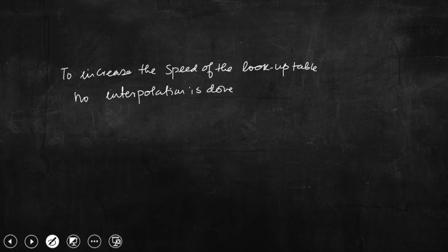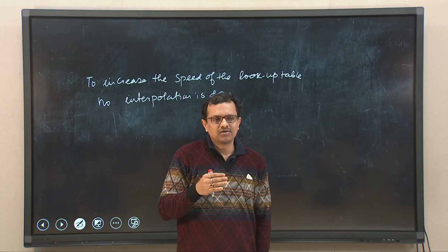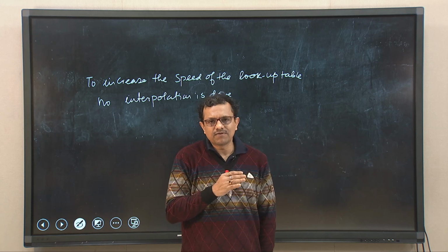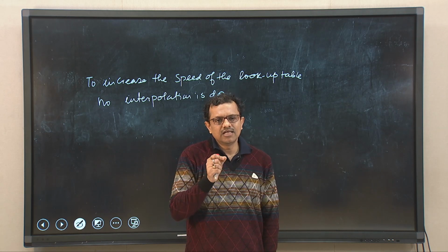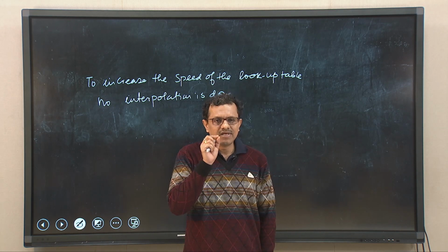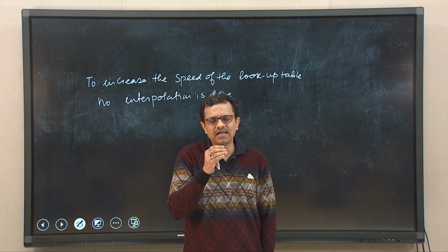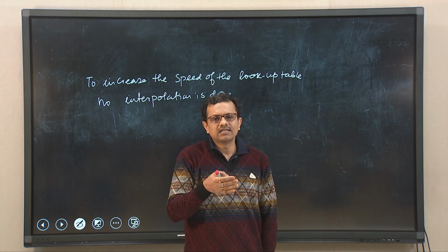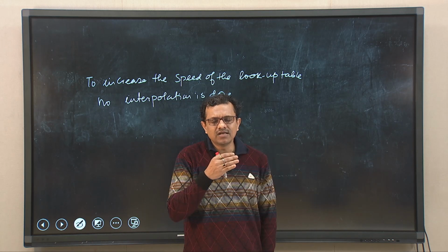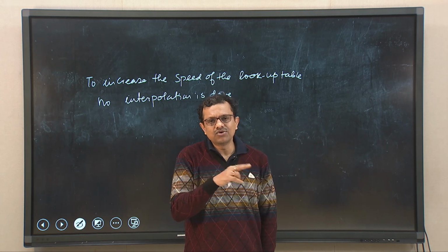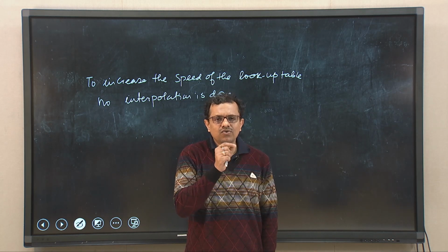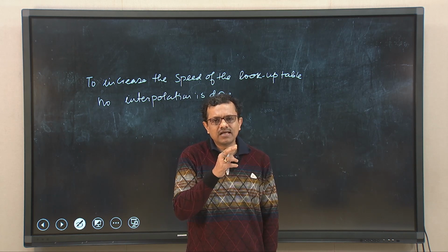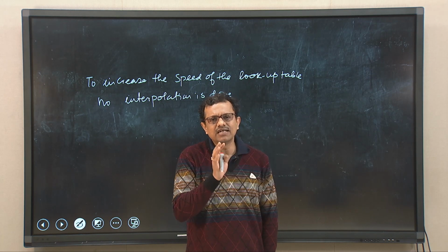That means, had we conducted the test considering a stoichiometric air fuel ratio, and measured engine speed, say, at 15 degree throttle opening and then also at 20 degree throttle opening, no interpolation is allowed in this lookup table to know the engine speed in between these two throttle opening angles, that is 15 degree and 20 degree.